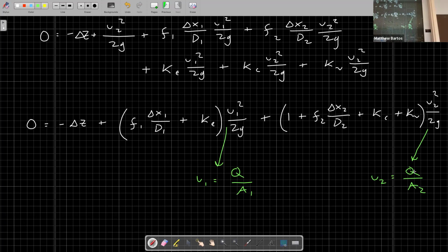Is discharge the same for the whole pipe? Yes. So by continuity, the flow going into the pipe has to equal the flow going out, or else there will be some accumulation in the pipe, which can't happen because it's pressurized and completely full. I know that that might seem unintuitive, but you can be sure of the fact that for any problem involving pipe flow, the flow coming in has to equal the flow coming out.